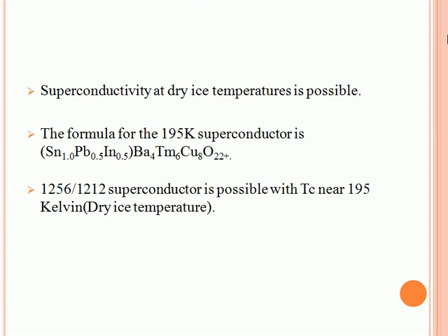And then we are looking for a superconducting motor that works at dry ice temperature. So we need to have the magnet material first that works at dry ice temperature, so we need to look for it first. To have a magnet, we need to have superconducting wire. It has to be an electromagnet. Can't you have a permanent magnet work at 195 degrees Kelvin? No. Do they all lose their magnetism? Yes.